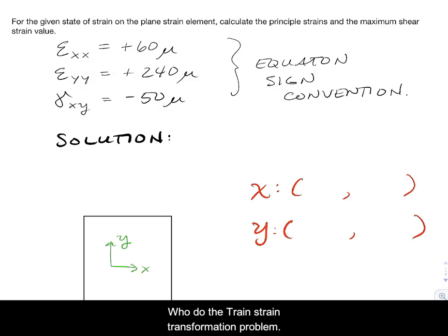We'll do a strain transformation problem. We'll end up calculating some principal strains and also a maximum shear strain. The other thing, we will also draw these elements at principal strain and maximum shear strain. So go ahead and read the problem statement.